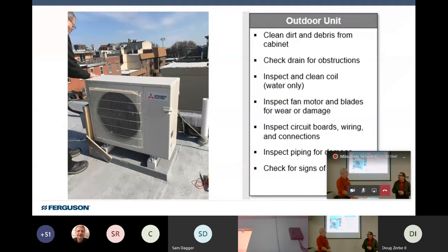And so you want to make sure that that line does have its insulation, that it's intact, and that we're fully insulated. Yeah, and as a tip, I used to carry at least one length of split insulation with the sealing gum on it, of one of each size that I would carry just to have it. And on a preventive maintenance, if it was bad or very deteriorated, falling apart, you walk up on some of these and it's hanging off the pipes.